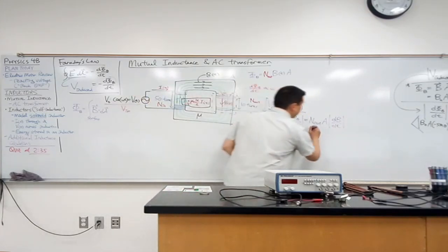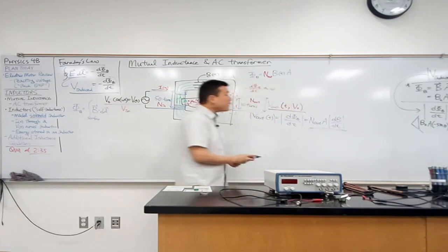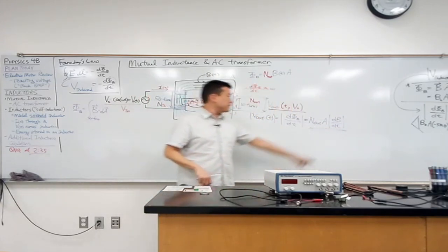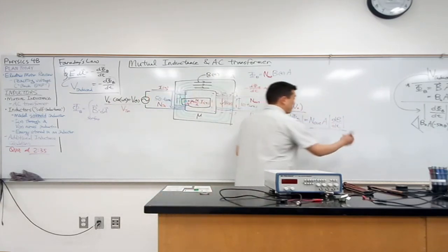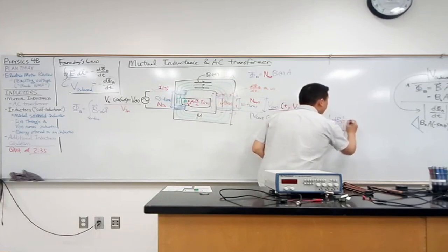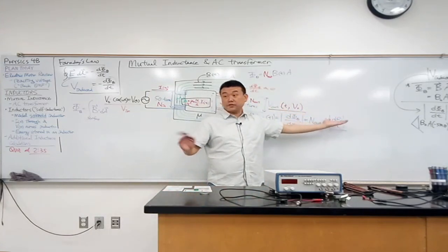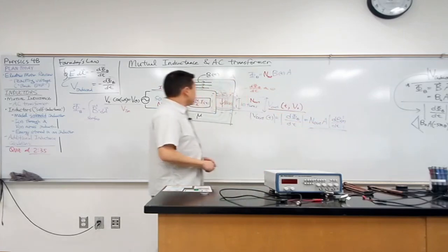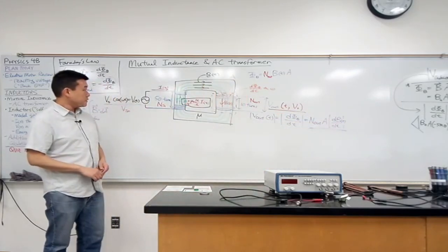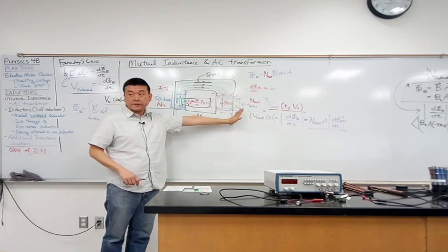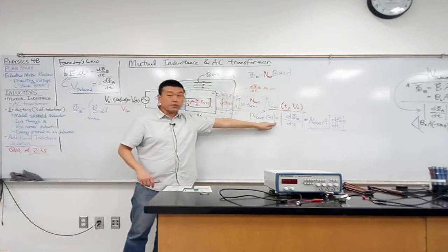So this is the voltage out here. And any kind of time dependence is inside the magnetic field. So if you are going to get something sinusoidal, the magnetic field will be varying sinusoidally as a function of time. So having figured this part out, that's what the voltage output is going to be.